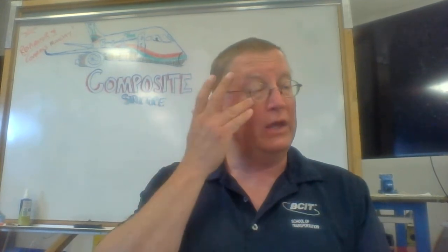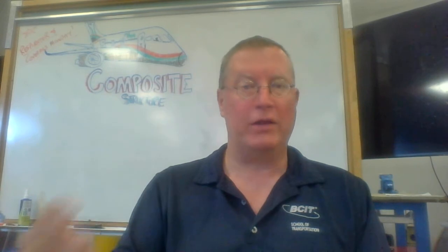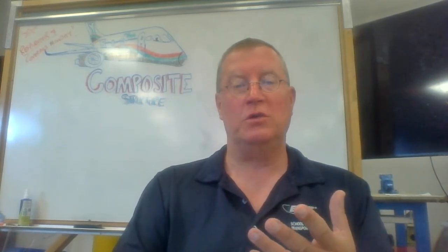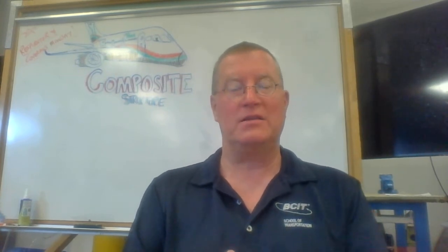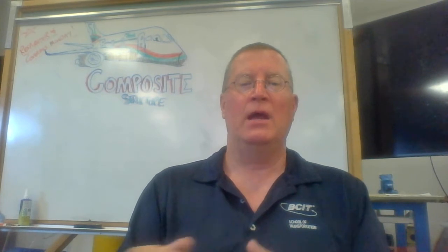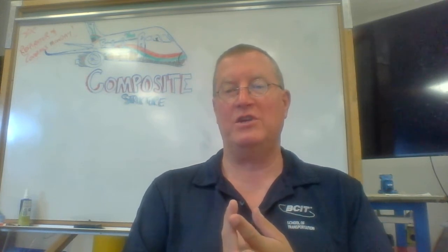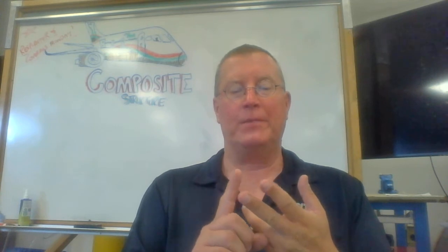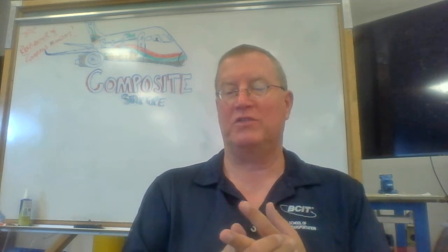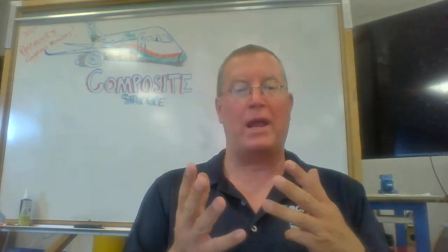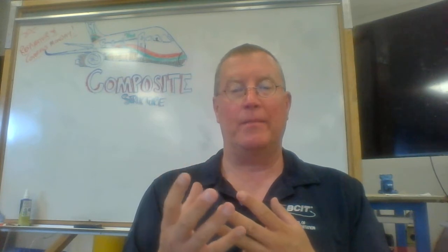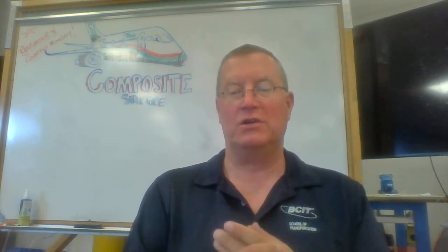What are the major pluses and minuses to each of them, and why would we choose to use those particular materials in a particular build? What advantage do they bring to the table that make them a good building material, right? And so we've got our base material, like glass, being in two formats. What is the pluses and minuses of each of those different types of glasses? Kevlar, we know impact resistance being the major plus, and its ability to be fractured or open up if it's damaged and absorb moisture. So that's its major disadvantage, right?